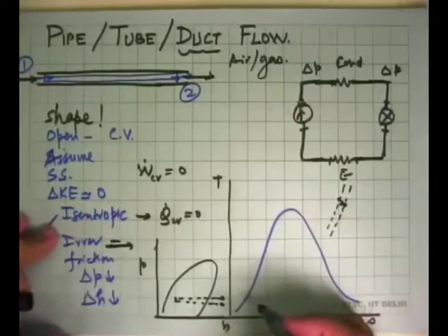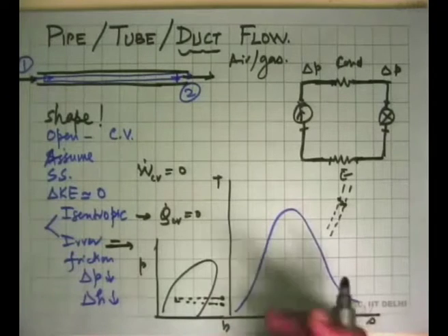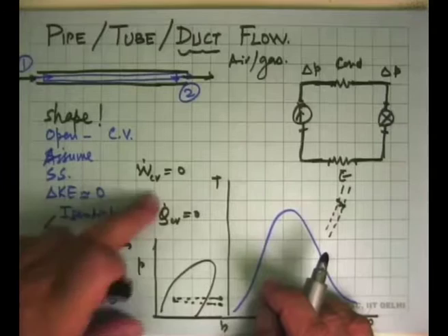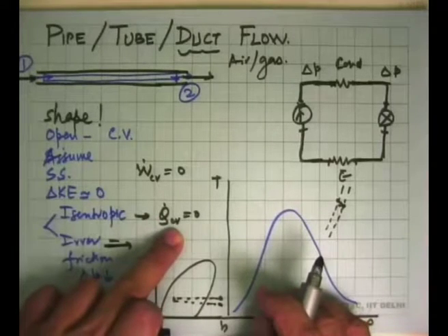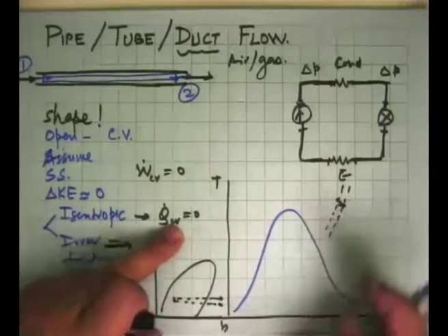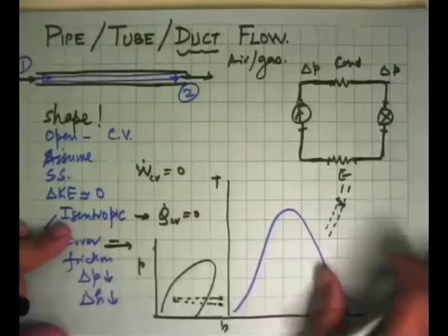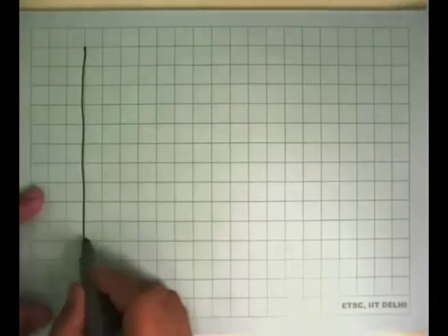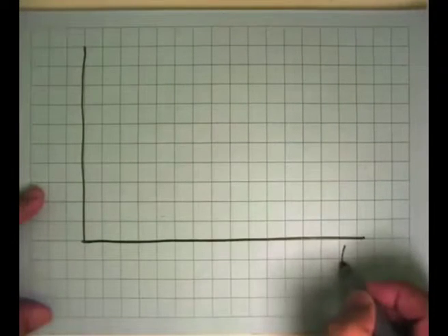Most of them are insulated, so we say, well, insulation is there and as a first approximation, we can say that it is adiabatic, Q dot CV is 0. And then the diagram which looked very simple will actually start looking a little more complicated. I'll just make one diagram as an illustration, and this is on the PH diagram.